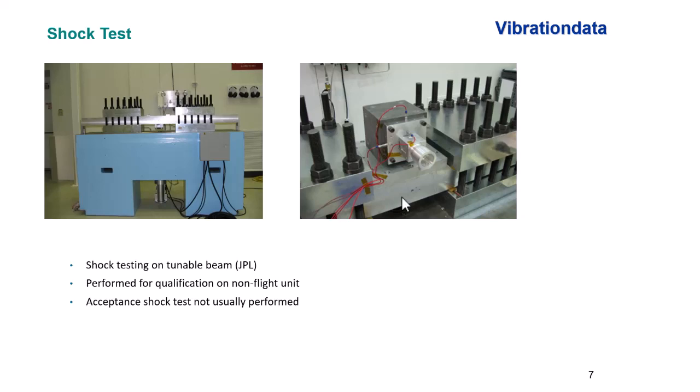So the test conductor picks which beam, and then he or she would then do some other adjustments. You see these blocks here have these tall bolts, and these tall bolts go into slotted holes. So these blocks can be moved to the left or to the right to control the length of the beam in terms of the inside faces of those blocks there. So that's another parameter the test conductor can control, for the setup, that is.